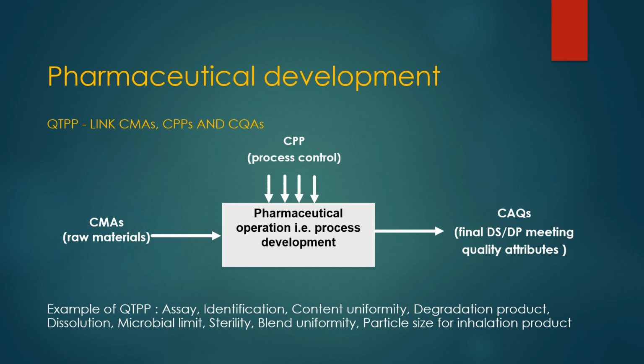For clear sterile liquid development, the solubility of input material and the selection of the right solvent to achieve a stable solution. These are the critical material attributes. The CPPs such as maintaining sterile boundary by selection of right filters, positive pressure of vessels, completion of successful SIP cycles, flow rate, mixing speed, temperature, and maintaining the closed manufacturing system integrity.